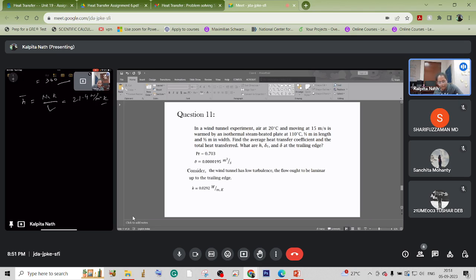You have got these values only, right? Yes, ma'am. Okay. Then heat transfer rate is overall heat transfer coefficient into area into delta T. That is 21.4 into 0.5 squared. Area is 0.5 squared because it is a square, right? Yes, ma'am. The plate is a square and its one side dimension is 0.5 meter.